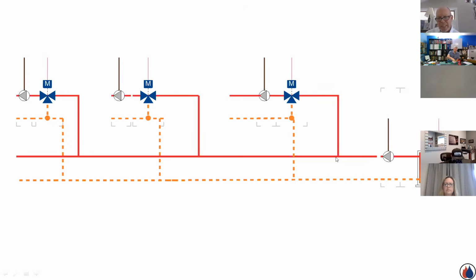Upon commissioning, as the heating season arrived and these things started to work, suddenly they were snapping the linkages. The linkage is a little arm that connects the actuator right here and the 3-way valve that has a flapper inside that repositions based on outdoor reset. And these linkages were snapping. So we finally got the call to come out and look at it.